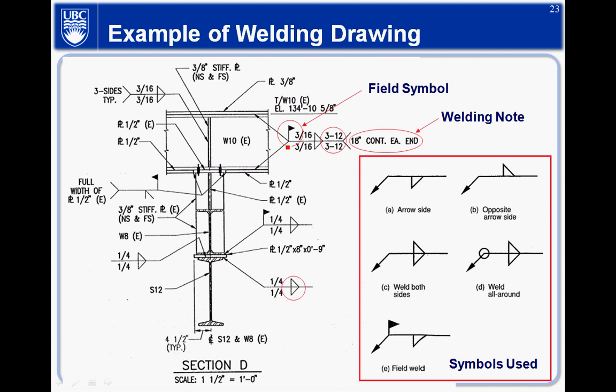Anyway, what I want you to remember or to understand is a couple of important things. Remember, this one represents the fillet weld, and this down here represents the arrow side. This is the other side. If there's a number here, that represents the leg size, because that's a very important value. You're going to need that. So those are basically the essentials I need you to understand.